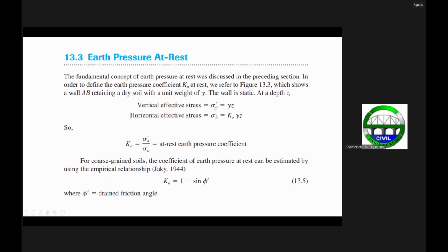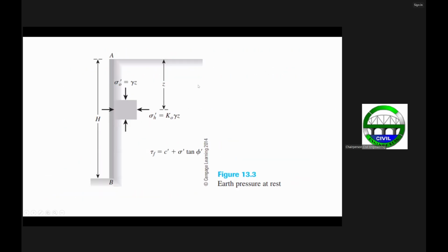So that's this one here, that's your unit weight. In this case, we have a dry unit weight material, for example. For the moment, let's just assume a dry unit weight, although in reality, there's no such thing as dry unit weight in the field. You can have maybe moist unit weight, then you can have saturated unit weight, but from there, you can derive the dry unit weight. The only time you have dry unit weight is when you oven dry the soil sample in the lab.